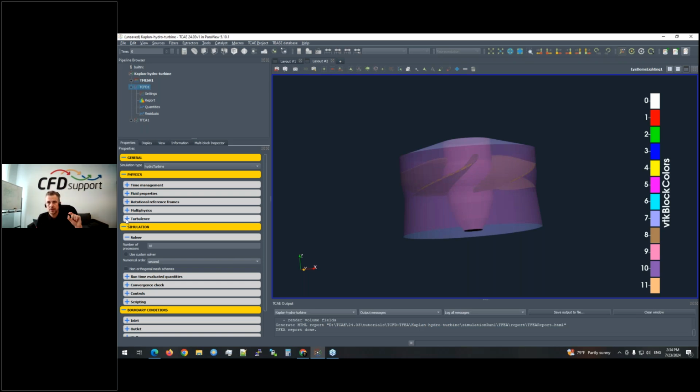It decides the final accuracy. When you already have something which is really good, then with turbulence you can make it perfect, right? But very often people think that the turbulence settings are important in the beginning, while boundary conditions, which are way more important, extremely important, are something which is set automatically. But it's the opposite. It's the other way around.